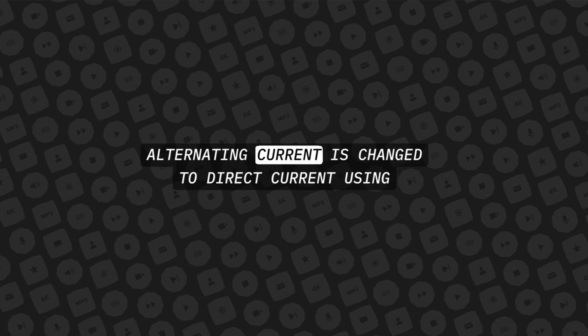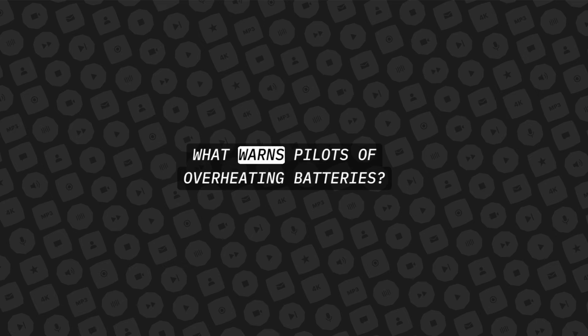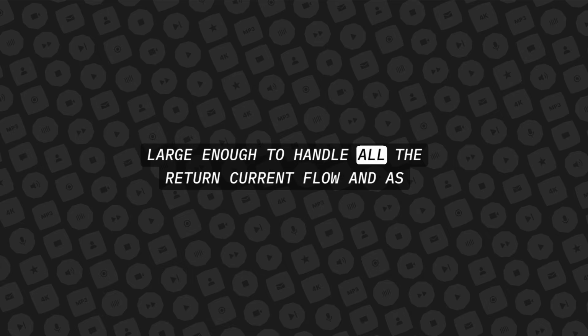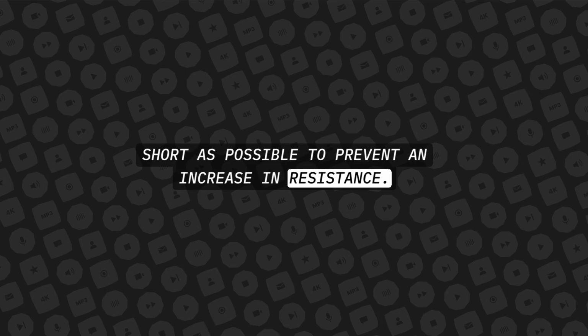The alternating current is changed to direct current using rectifiers. What warns pilots of overheating batteries? A thermal sensor in the battery and a light in the cockpit. How long should bonding jumper wires be made? Large enough to handle all the return current flow, and as short as possible to prevent an increase in resistance.